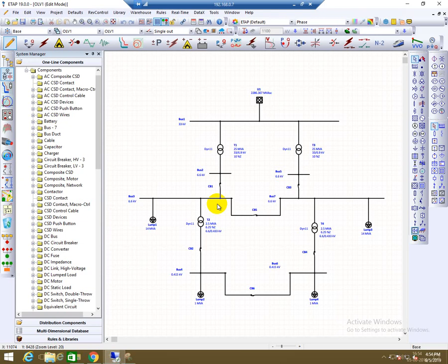In any electrical network, we want to know the load flow throughout the network, because if any fault occurs in the circuit, and you know how the load has been distributed and how the percentage of current and voltage has been distributed across each branch of the network, then it is easy to calculate the fault current and the fault voltage, and we can design the protective devices for particular places of the network.